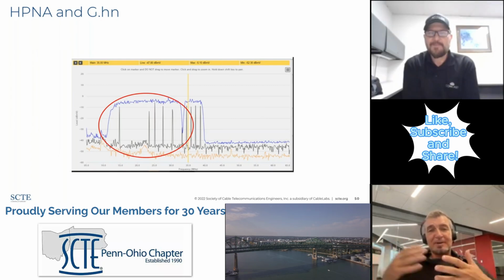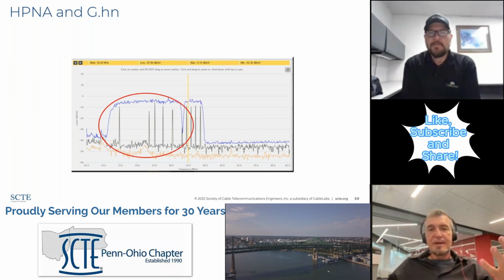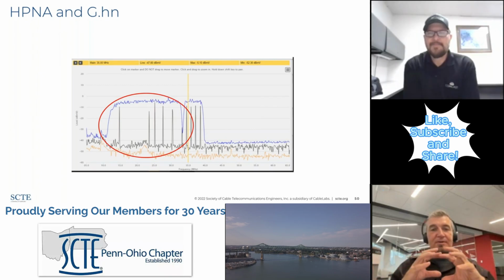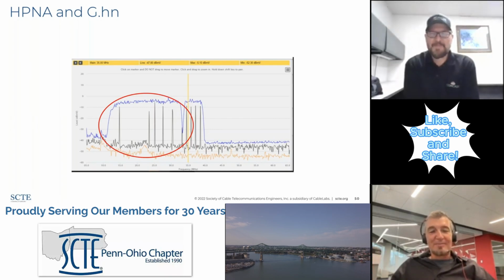In-home signaling from box to box on U-verse, for example, uses HPNA, and certain FiOS and a couple of others, where they will basically take the existing coaxial in our houses, connect the boxes, hey, it's conveniently there already, and they'll transmit from set-top box to gateway using our coaxial cable in our upstream frequencies, which is in theory fine, except if you leave it connected to our plant, you basically now have an OFDM signal generated that's interfering with our return frequency spectrum, and so that's exactly what it looks like.